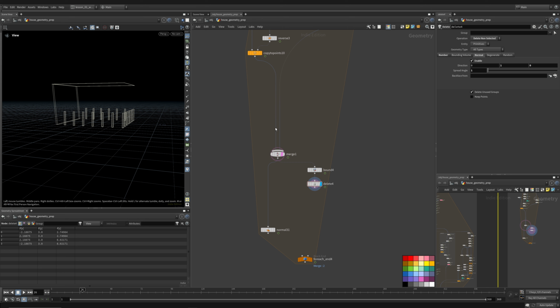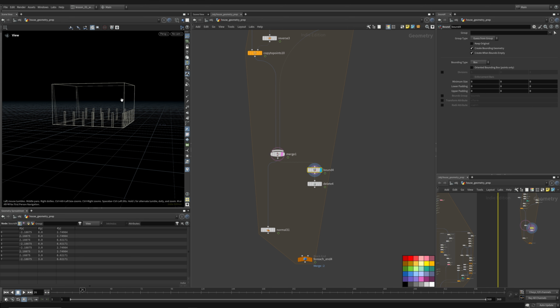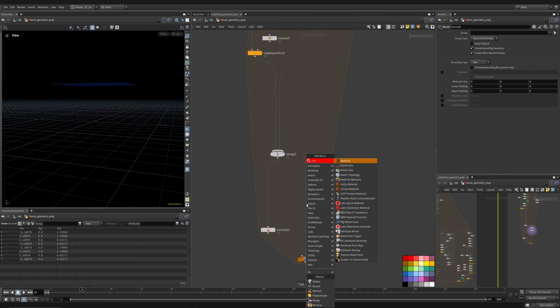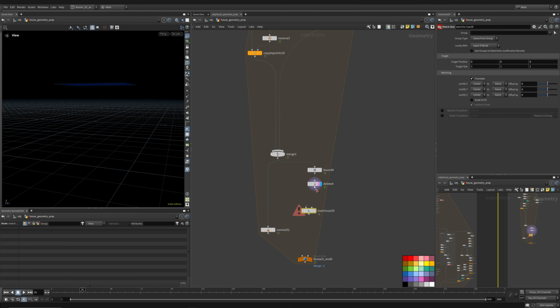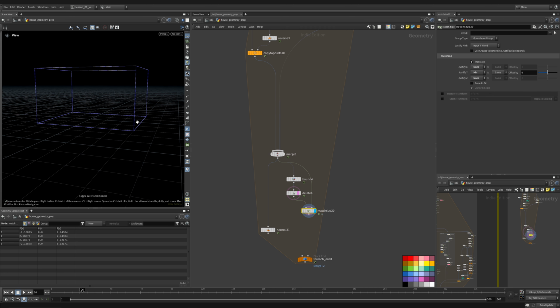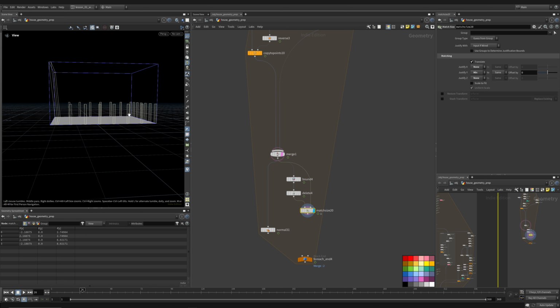So actually I could snap it down to the bottom, or I could have just used the bottom side of this box, but I will actually snap it to the bottom to show you how to do that. So I can use a match size again. I'm going to rearrange this object here. Snap the none on X, none on Z, and min on Y. And there we go. Now we have the bottom of this grid, which is the size of this entire thing.